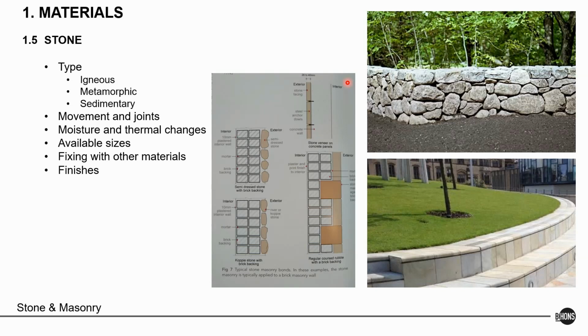Then they come in various sizes, and the only advice there would be, if you use stone, we don't often cut it into blocks anymore, as you would see here. This is really an expensive process, but you can do it. We often use it as tiles or as thin veneers that we fix on, and that can actually be fixed with simple tile cement. Do speak to the suppliers of the tile to see what's properly needed, because if you start going for very heavy, large tile pieces, then you have to start looking into aluminium or steel brackets that you fix onto the wall, and then you fix the tile onto that. So it's all dependent on the weight of that tile.